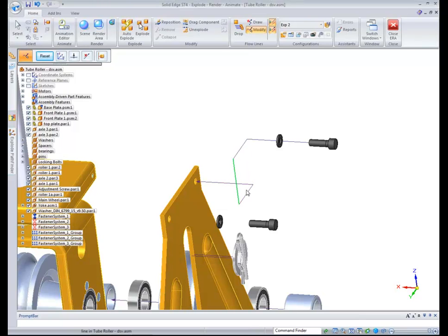And if you drag it out here and you decide to move it back, you just come to the edge of that line and it'll line it up with that. They also have the command to split flow lines. So you can come in here and split this, and let's say maybe it needs to go around a part. Then you can just select this section that you split off and move it around whatever part you need.